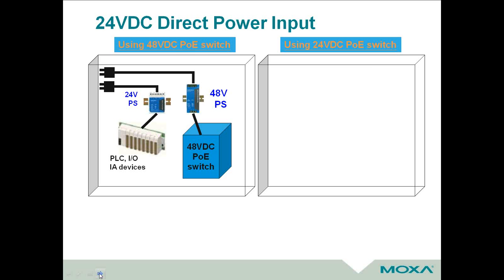But let's go back to some of the advantages you can expect to see when you use Moxa that really don't exist in a lot of other commercial players. So, if you want to do an industrial PoE solution, these are things you should consider at least. PoE does send out 48-volt DC, so you would expect that the device that's providing PoE also needs to be powered by 48-volt DC, right? Well, in most cases that is true.